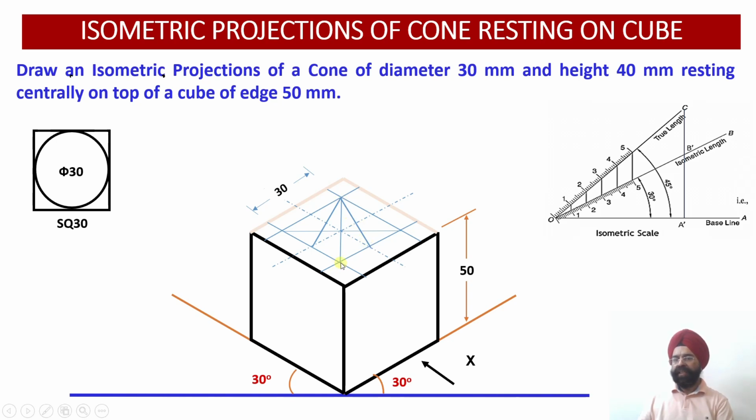Similarly, this is the second end of the minor diagonal. From here, you have two opposite edges, these two. These are the midpoints we have already marked. From here, you join this midpoint. From this point, you join this midpoint. So this is the four center method.